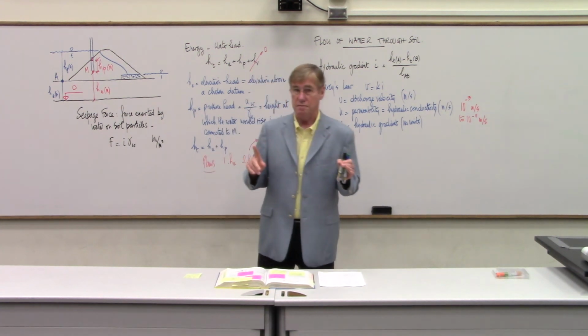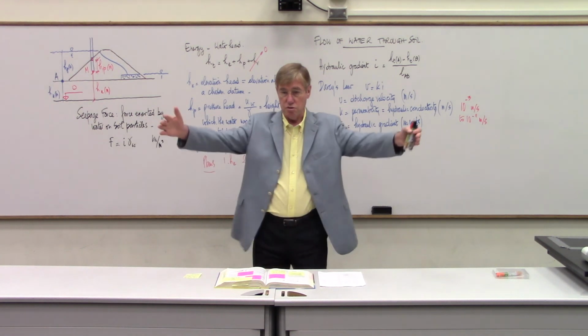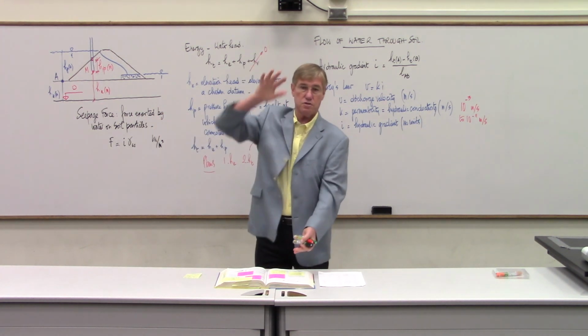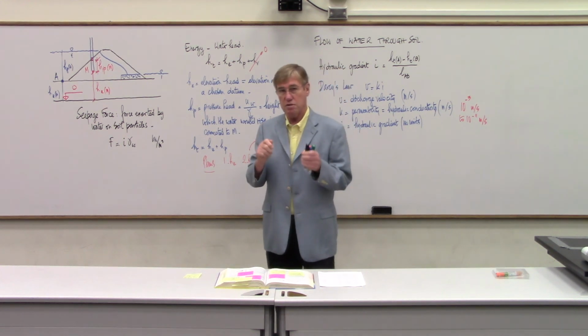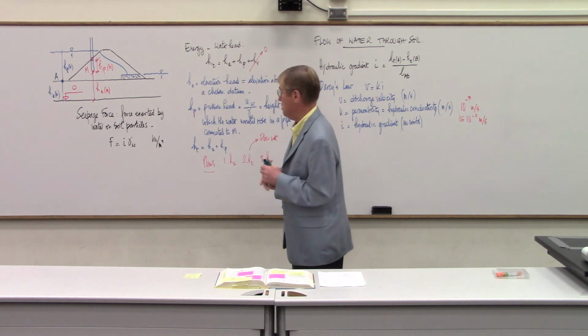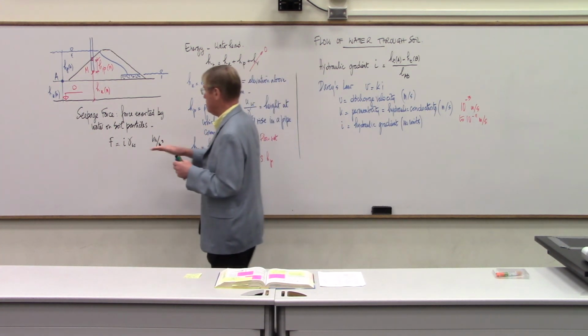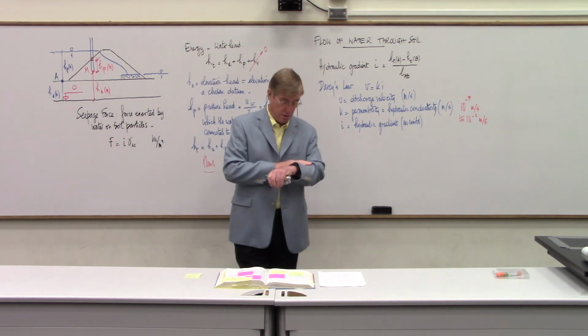That's 1 ton. 10 kilonewton is about 1 ton. So you're looking at 1 cubic meter of soil, and the water going through that is exerting 1 ton of force to push that block of soil downstream. So it's very sizable, and it can create a lot of trouble, as I mentioned, through erosion.